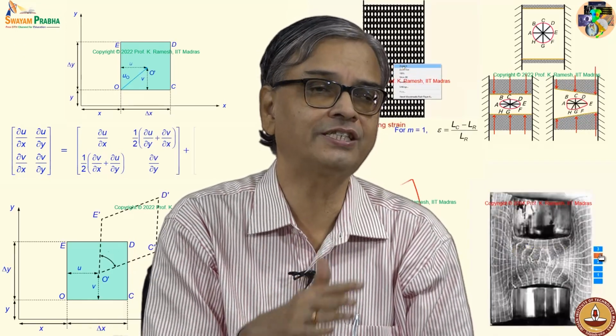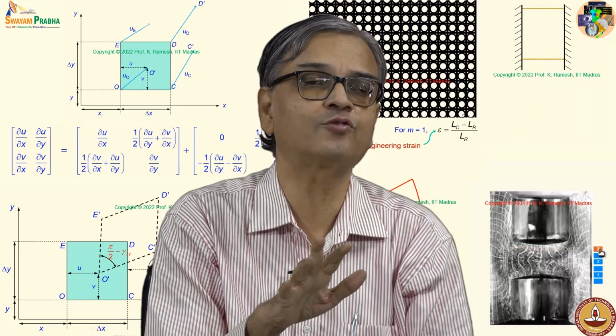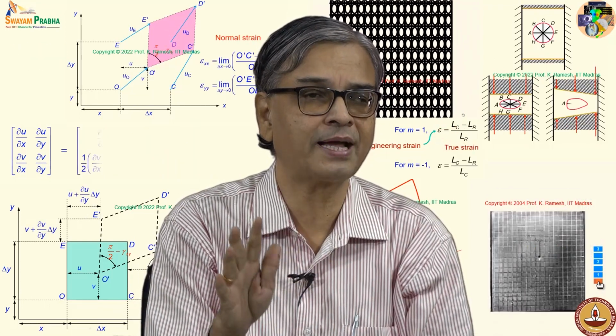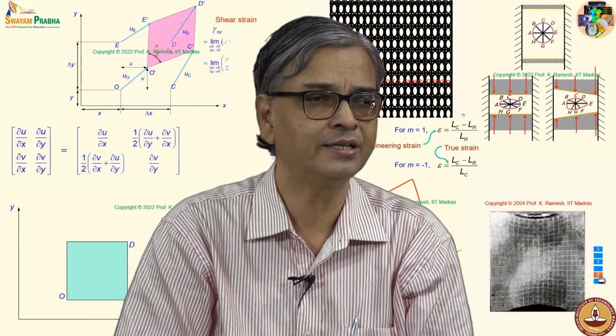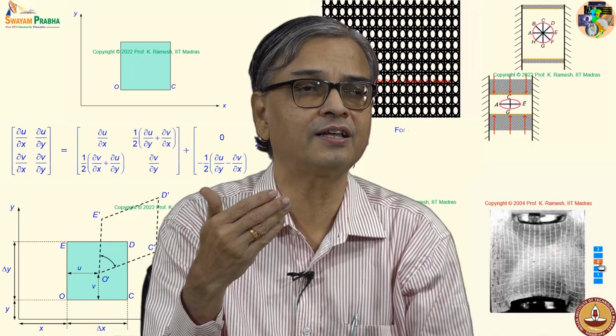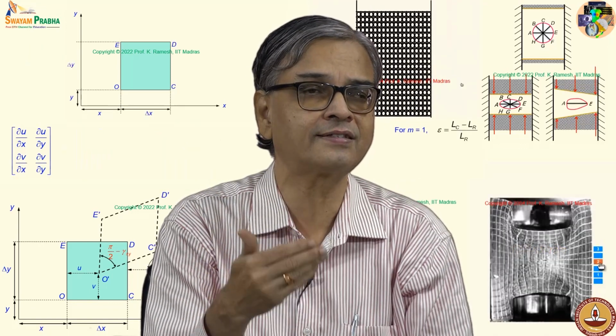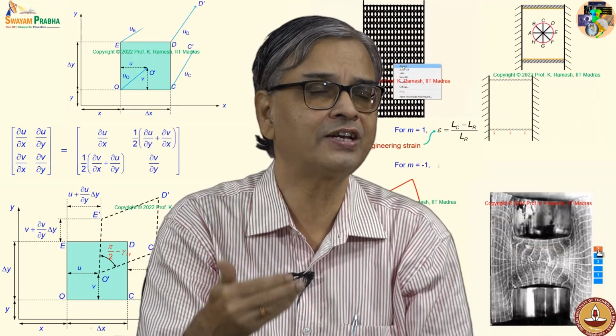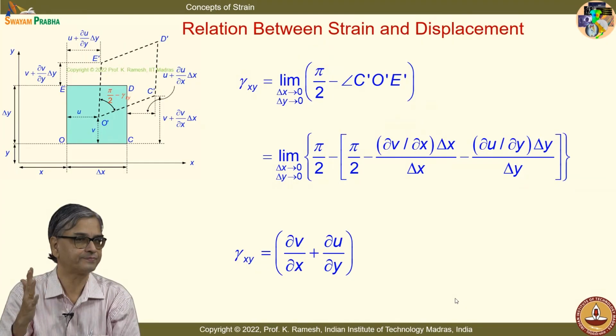Now what we have achieved is, we have recognized there is going to be a displacement field. From the displacement field, by applying Taylor's approximation, we are now able to express the quantities like epsilon xx, epsilon yy as appropriate partial differentiation of u and v.